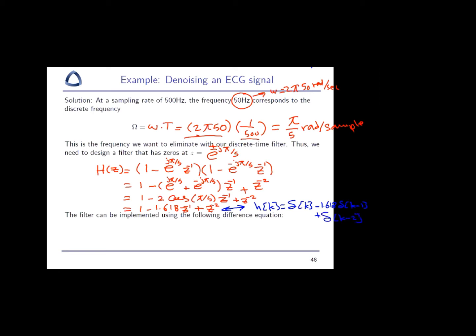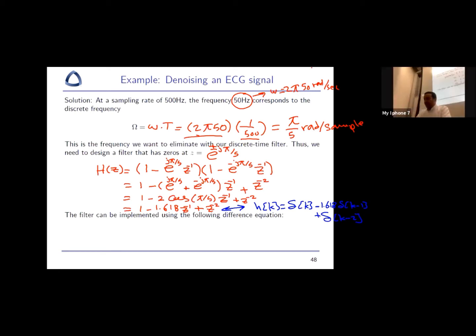So that's the filter transfer function, and also find the difference equation of this filter, which is y of k. Again, remember this equals Y of z over F of z. Multiply both sides by F of z, and then find the inverse. There's always similarity between the transfer function, the frequency response equation, the impulse response equation, the output equation, or the difference equation for simple systems. So this equals what? You can take that directly from here.